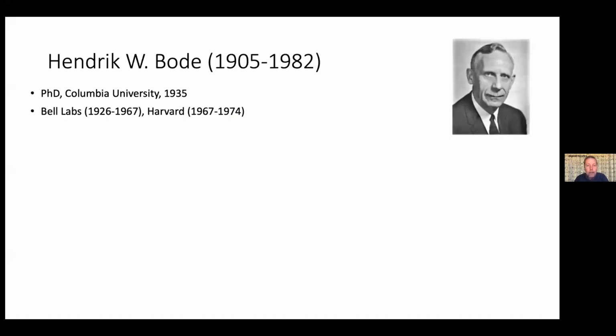So this is what Bode's integral states. It says that we have a function S, the sensitivity function, which if we take the logarithm of that and we integrate it from 0 to infinity, it vanishes. That's what it says. Of course, I will come back and talk much more about that. But let's start with a little bit of historical reflection about this amazing guy, Hendrik Bode.